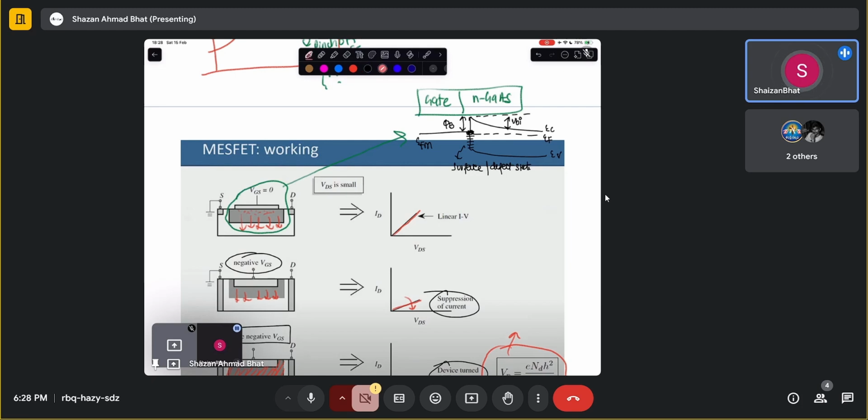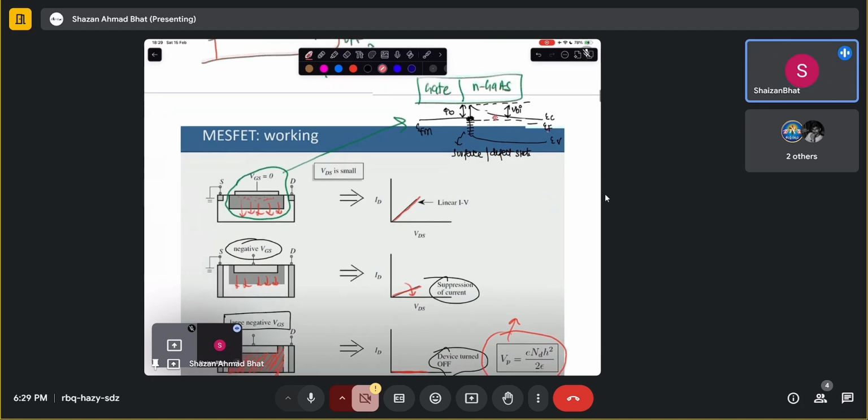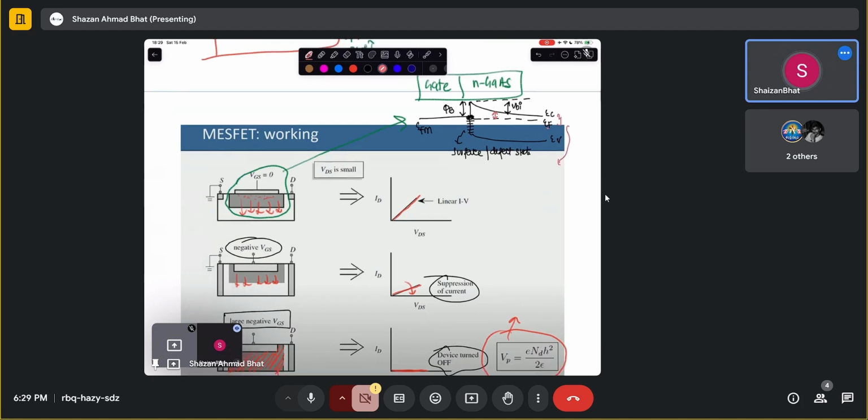And then you can find this particular voltage, which is basically EC minus EF. It can be found approximately by phi B minus, let's say, VBI. Not exactly from this, but you can compute this particular EC minus EF as kT by q ln of NC over ND, if this is doped with ND.